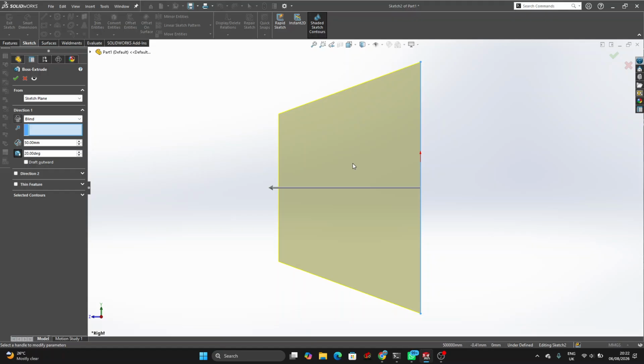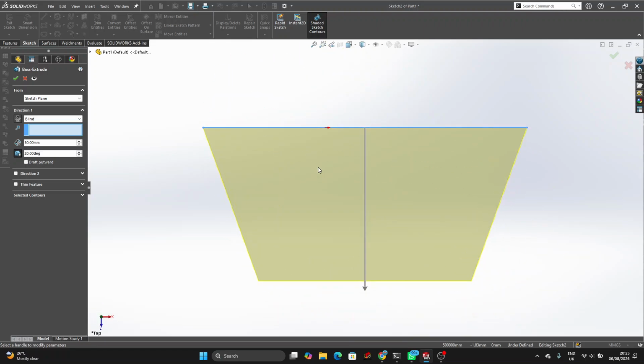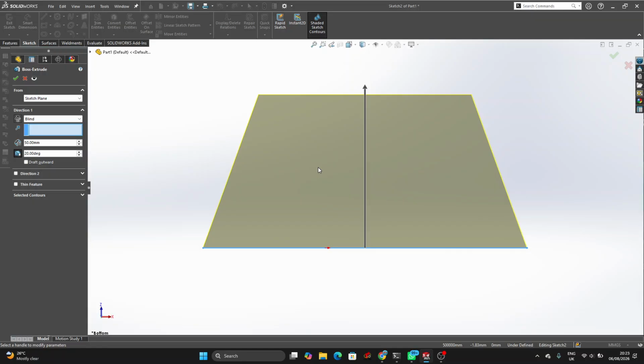I know you are getting what I'm doing. Control 4 is right view. Can you see? Along all those views, it's still the same. Yes, sir. The angle is 15 degrees. Control 3 is left view. If you are following me, Control 5 is top view, like I said before. Control 6 is bottom view.